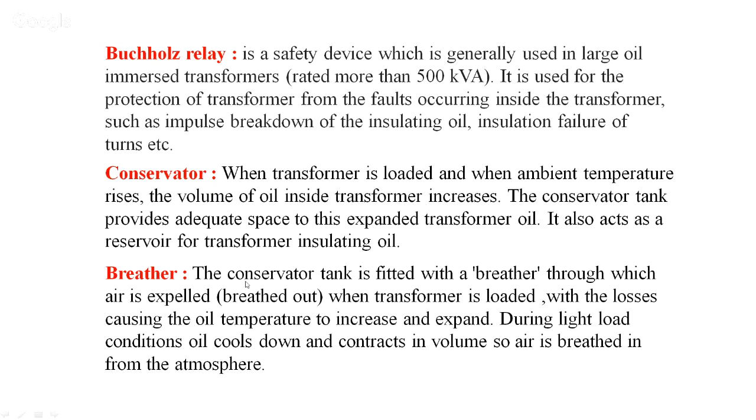And breather is fitted on the conservator tank, through which air is expelled or breathed out when the transformer is loaded, with the losses causing the oil temperature to increase and expand. During light load conditions, the oil cools down and contracts in volume, so air is breathed in from the atmosphere.